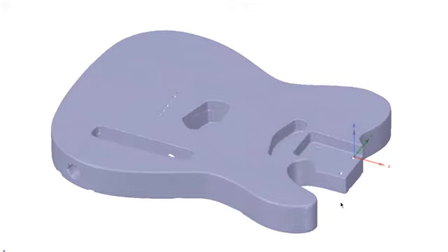Okay. And how far should the laser be from a part to acquire proper data or the best data? The beauty of the laser line probe is that we have a rangefinder built into it, and that also pops up into the software. So as long as the laser scanner is within about 50 to 150 millimeters of the surface, you're going to acquire good data through that whole depth of field.